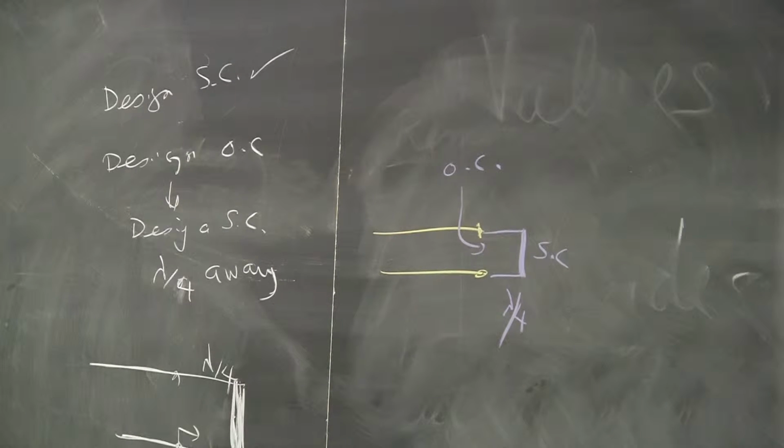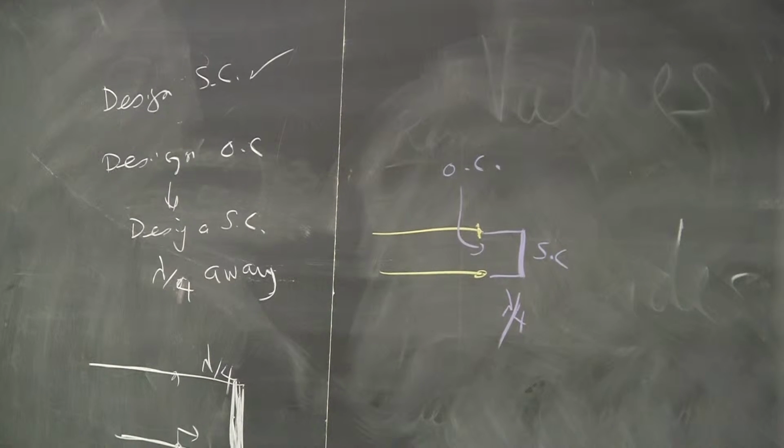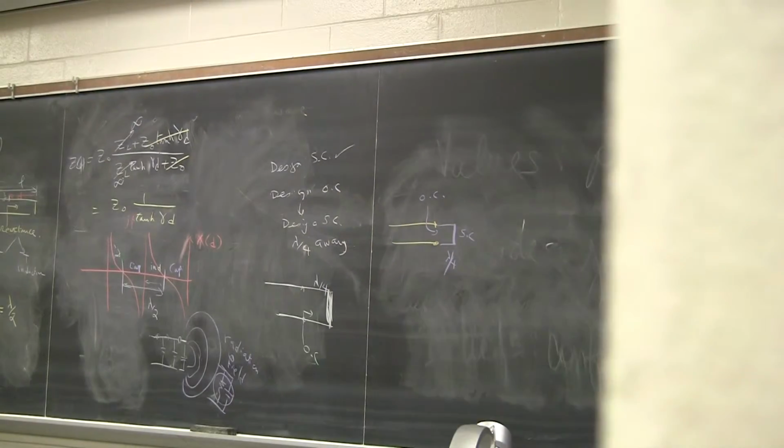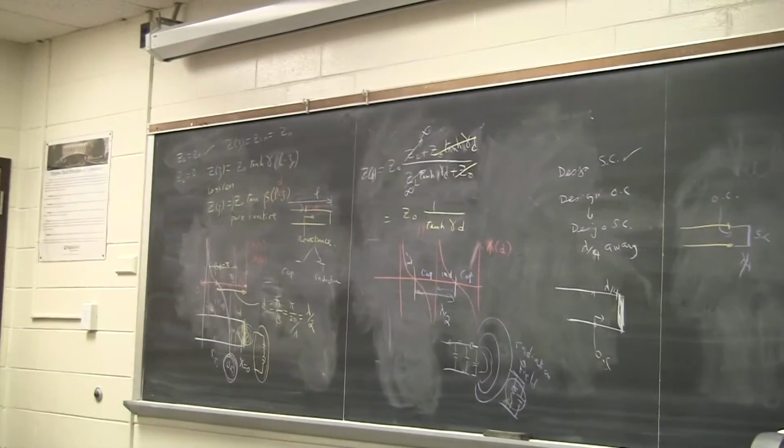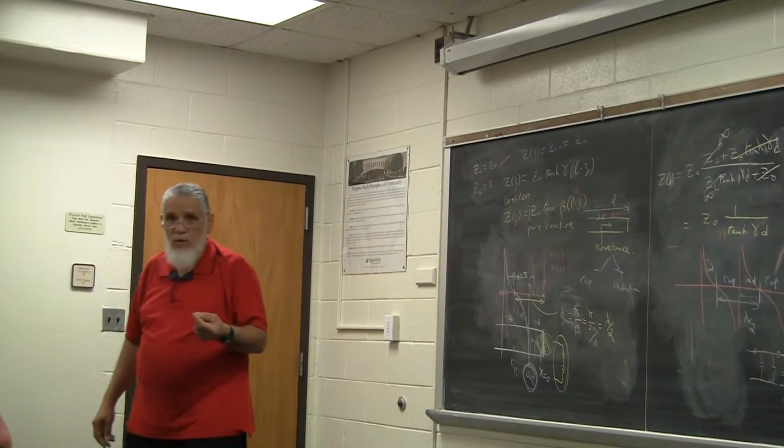So when you go to the lab and you do a calibration to a network analyzer, one of the types of calibration that we make is we do an open short load, right? OSL, or sometimes OSR, open short load.